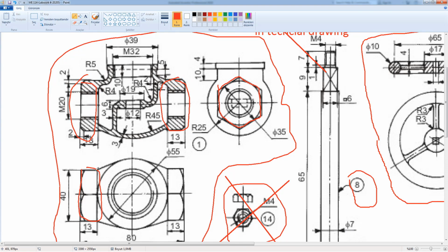After this one, I will create a body part by using some measures or some path tools with the loft tool. Also, I will remove material with the revolve tool and add the inside feature here, which I'm going to use on this body part by having the extrusion with two commands.